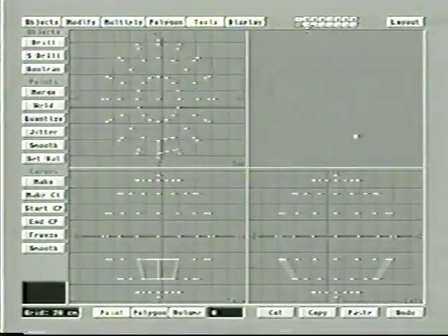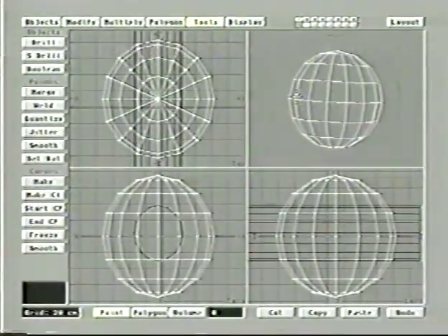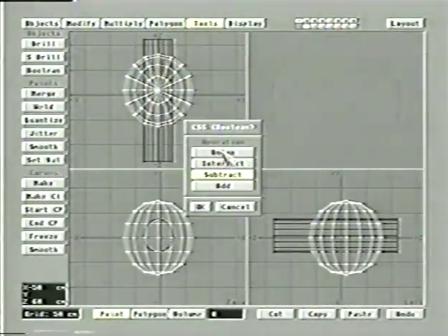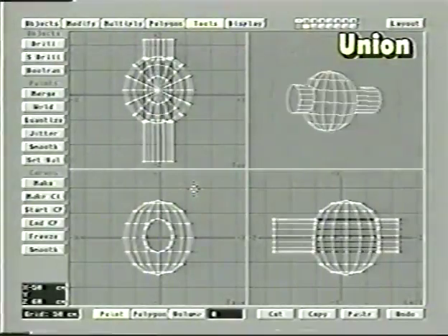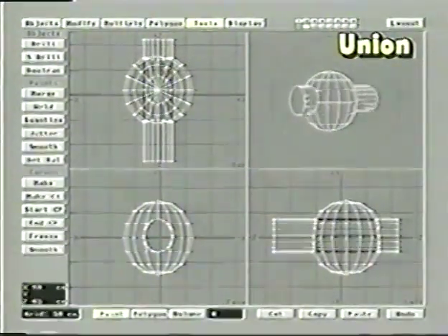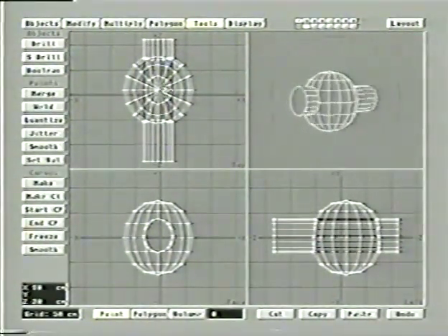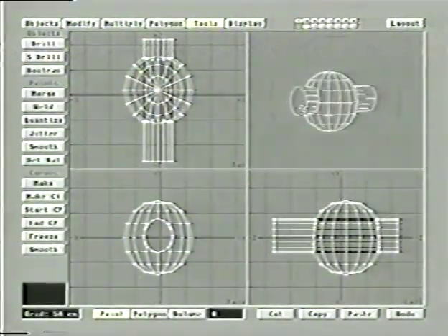Now, just reselect layers 1 and 2 here. And again, I'll have layer 1 active, layer 2 inactive. And let's talk about the other Boolean options, namely, starting at the top here with union. What union will do is it combines the two things. But what it does is it actually adds the background or inactive layer to the active layer and takes any parts that are in common and removes them. In other words, it's combined this, but there's no disk part in the middle here. And this is actually another fairly handy tool to use.